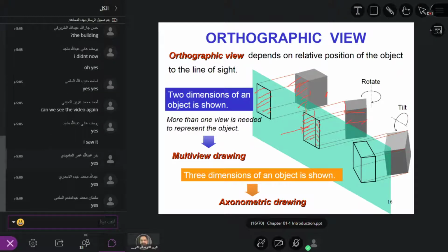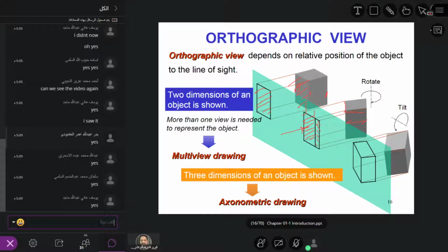So that's why, as an engineer, you should be very careful in visualizing the surface you have seen. The idea is you just keep your eyesight parallel to the edges, but if the object rotates slightly, then you will see different edges. Then based on the edges, you should draw the view. And remember, this view does not show the actual width in that case. So that is very important to remember.